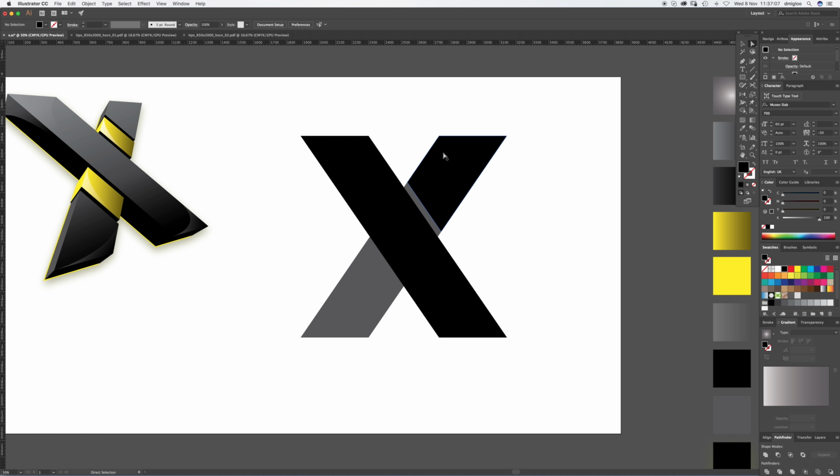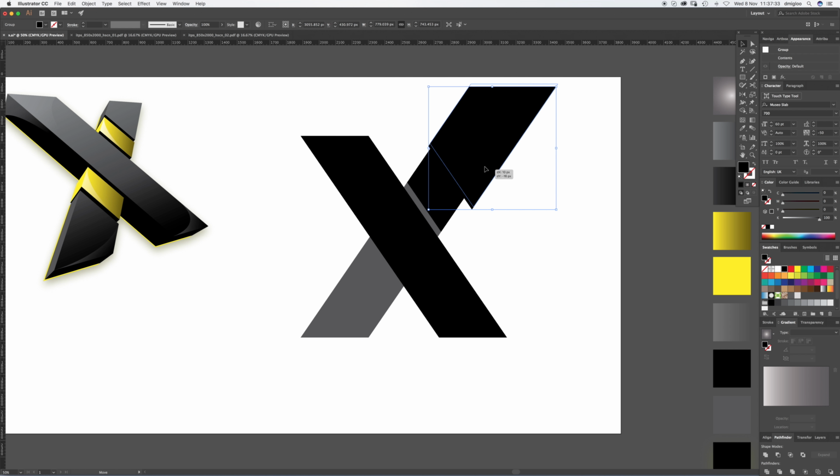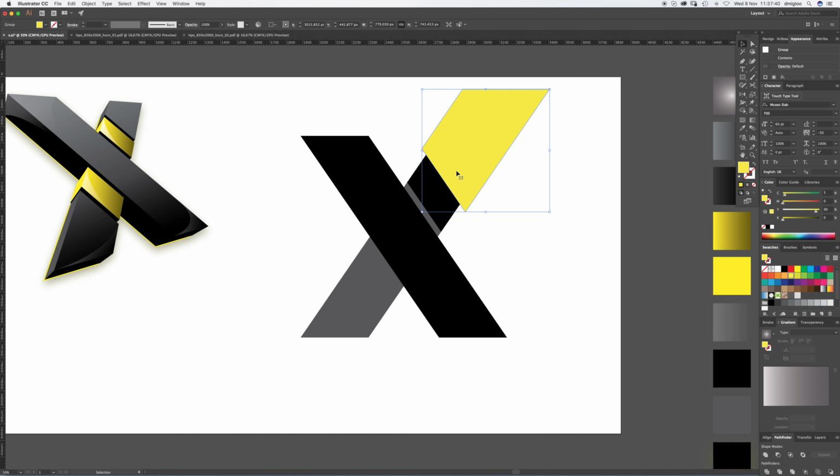So the next thing we want to do, we want to chop another shape off up here. So if we just go with this one and Alt, Shift and direct select with A, Alt and Shift gets us another shape. Now if you press V, I'm just going to drag this out, holding Alt and Shift, and make it a bit bigger. Okay, so how big do we want it? There. Now if I just change the colour of this one, you can see what's happening here.